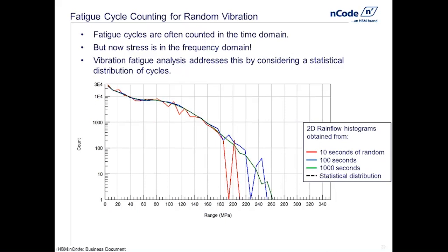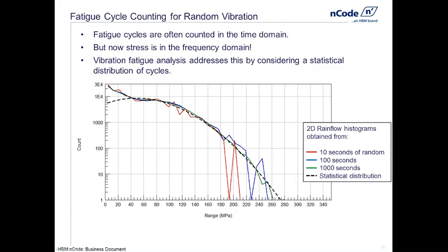The tail here on the right side is important because in fatigue, it's typically big cycles that dominate. The things that damage the most are the big stress cycles. So our ability to understand statistically the big cycles that happen under random loading is critical to fatigue. The cycle counting approaches all come down to what statistical distribution best fits measured data of random phenomena.